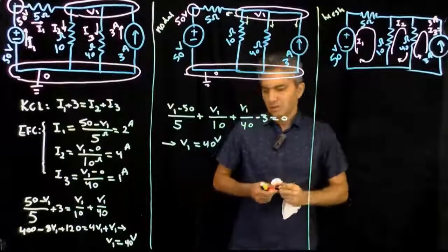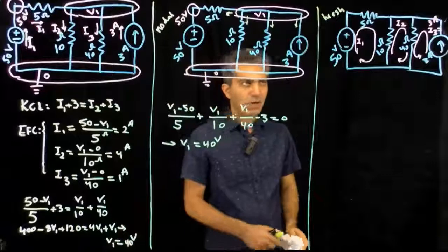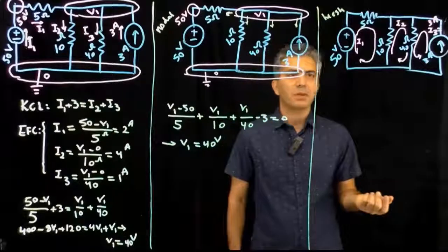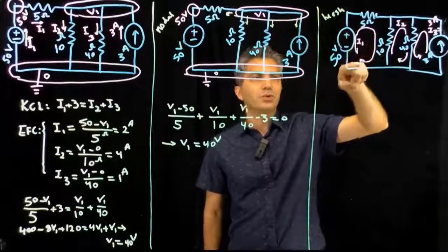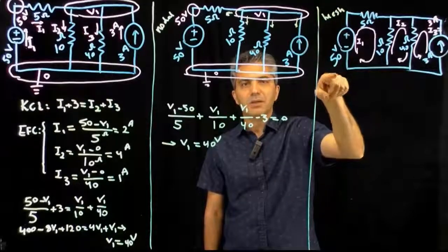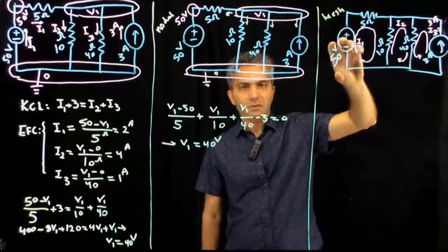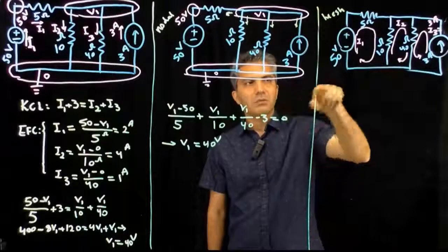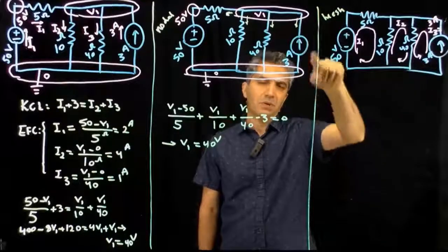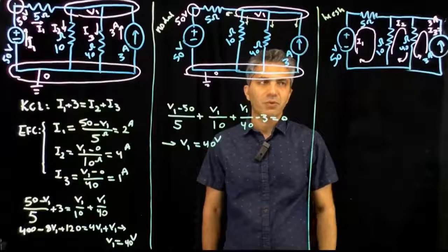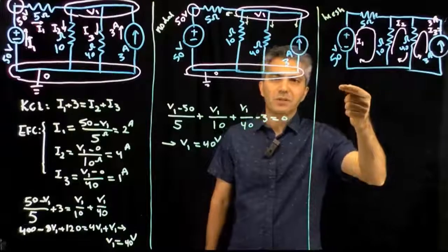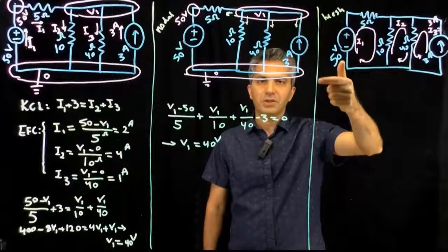Good. So then I'm going to start doing something that is called KVL. We haven't discussed KVL, but it's a very intuitive concept. What it says is that if you start in a loop, you start from any point in the loop, go through all the components and go back to the same spot, and you add up the voltages across all the components, then when you go back to the same point, the sum of all the voltages has to be equal to 0. Which is kind of obvious, in the sense that voltage shows the differences in potential energy of the system.